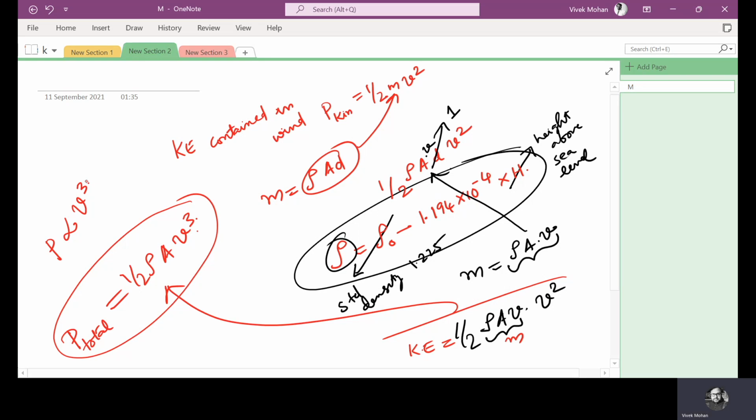So it is crucial to site the wind power plant properly, because the wind speed of that particular site is very important. The power that can be produced from the wind power plant installed there is proportional to the wind speed cube.